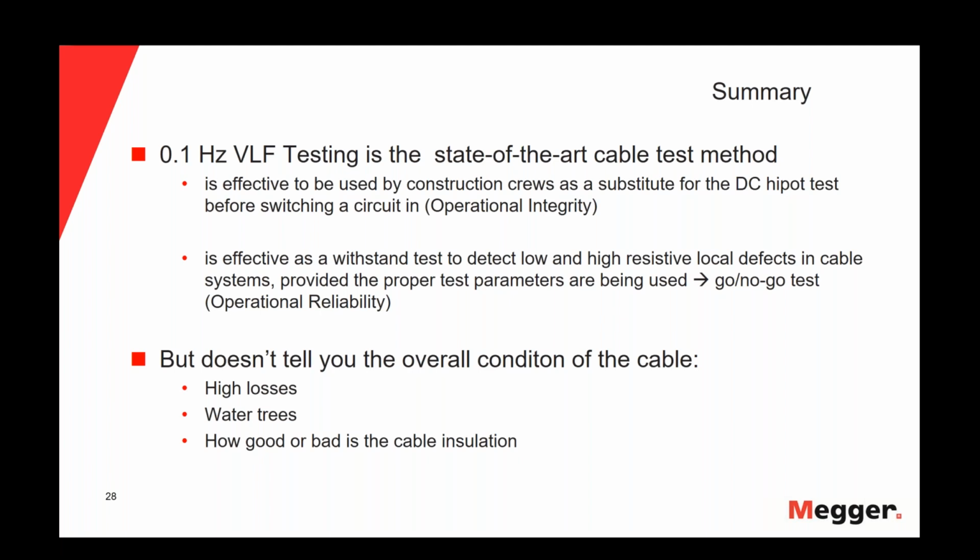That is something that happens very often. People are afraid to apply high voltage to the cables or to do the VLF test for the time of maybe 30 or 60 minutes. If we decrease the voltage or the test time, we are not doing an authentic and true VLF. We are doing a fake VLF test. So we always need to use the voltages and test times recommended by the standards.